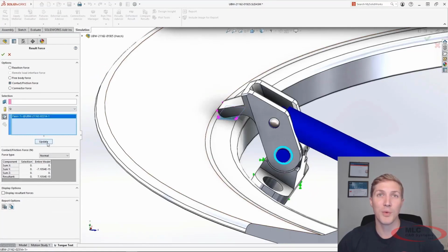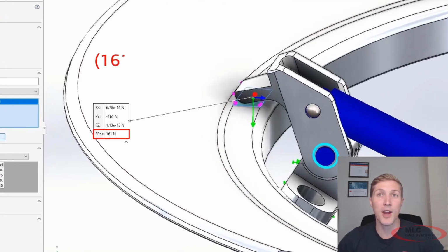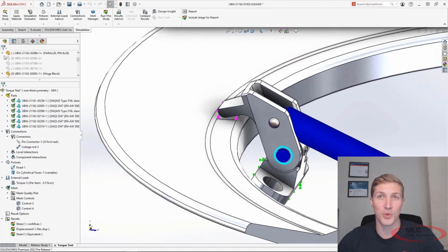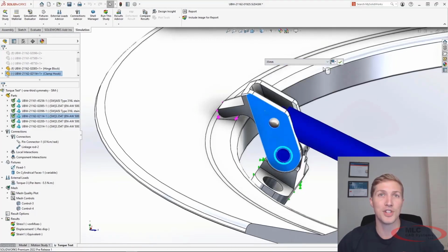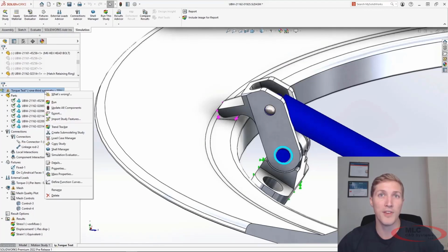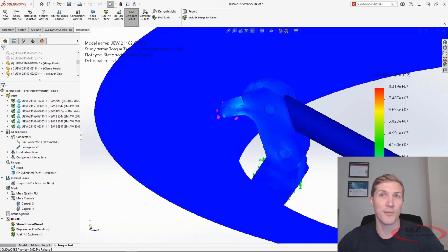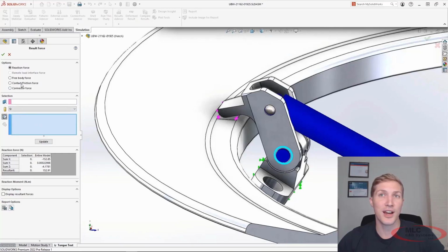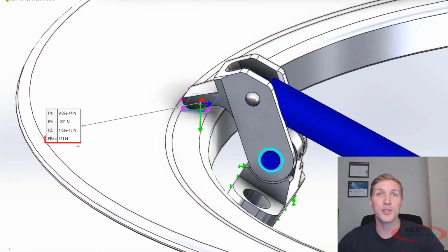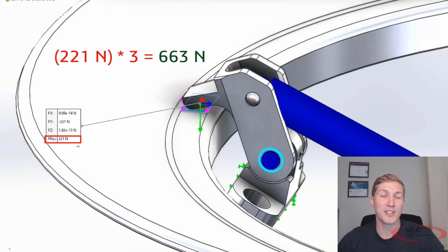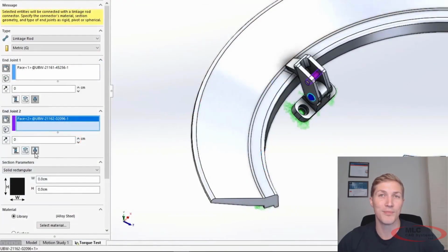Multiplying this contact force by 3 is less than the 500 newtons requirement to properly seal the hatch. So my options here are either make a design change or drown. So let's opt for design change and try moving the connecting rod attachment just 10 millimeters further away from the pivot, effectively increasing the lever arm. This should add additional contact force without requiring additional input torque. Now this small change increased the contact force by 38%, and we're now safely past the 500 Newton minimum and no longer have a single-use submersible vehicle.